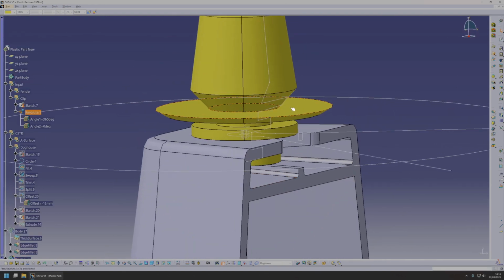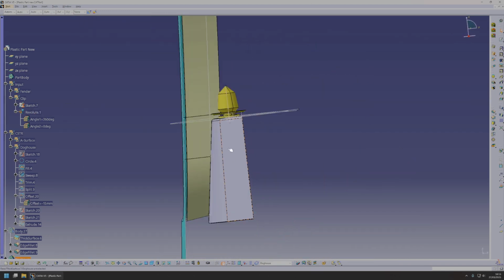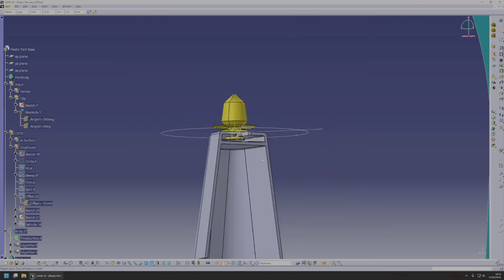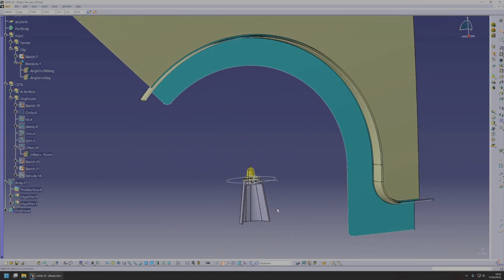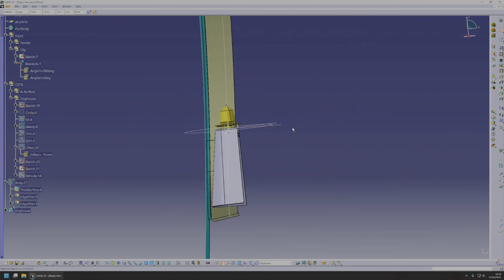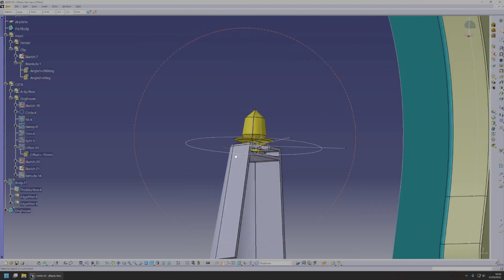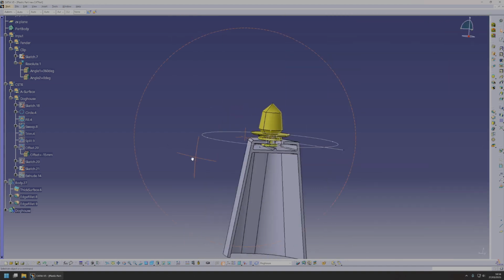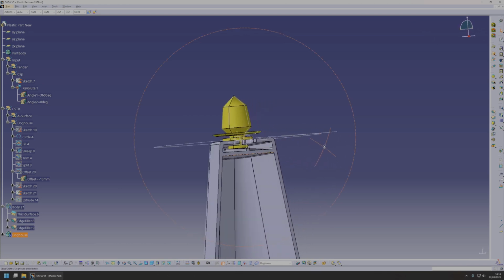The way it works is you slide this clip in, and this will keep it leveled. So this one you will be demolding it in this direction. It'll be a secondary direction from the main body. You have a slider that goes into this little pocket here. Once the mold opens in this direction, this slider will slide in and out like this, perpendicular to the main direction.